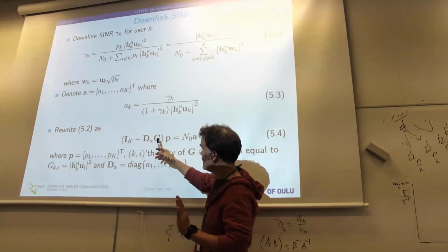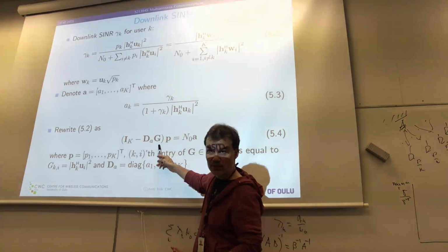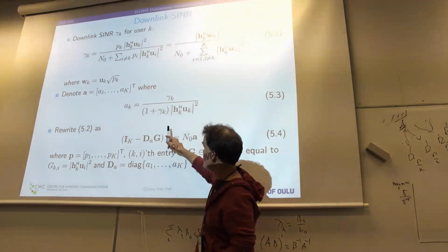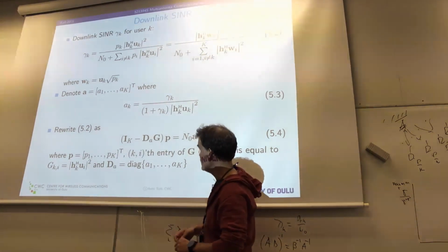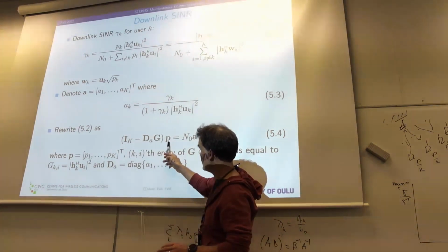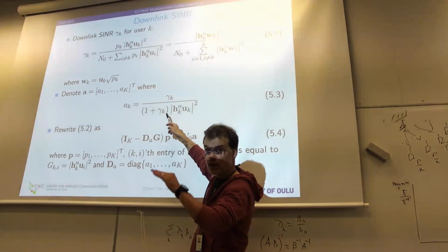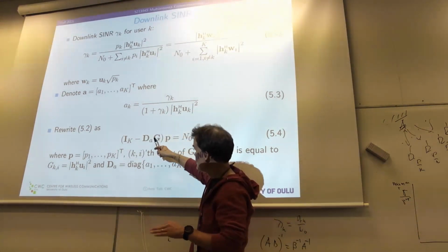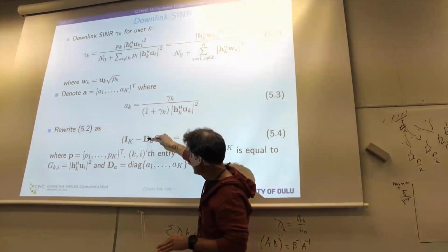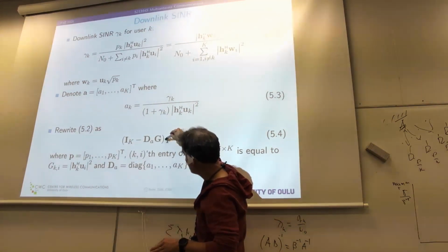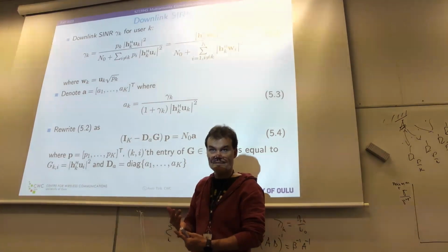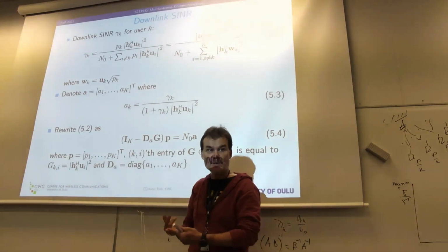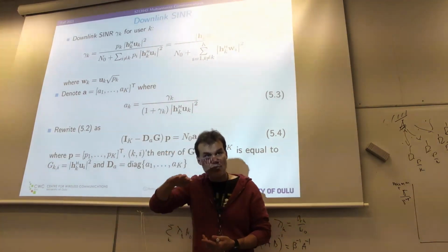Note that this can be also infeasible, meaning that especially when you apply match filter there, when you invert, when the SINR target is too high, you plug in this gamma in here, invert, compute the P, some of the terms can be negative, which is the sign for infeasibility, right? Meaning that gamma is too high.